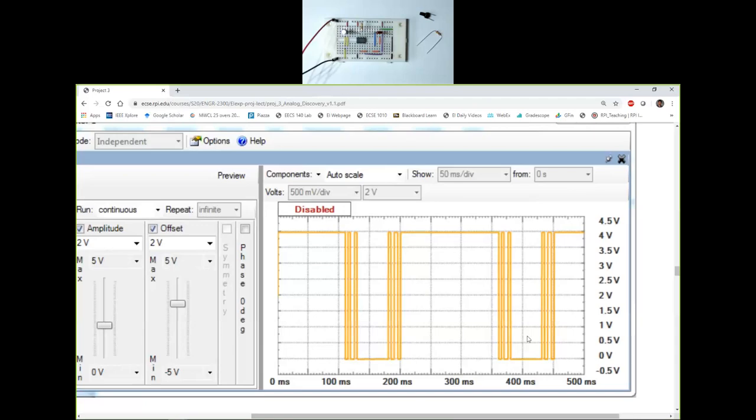a fake data that is essentially in a CSV file right now. We are going to import that, and it's going to look like this, where clearly those two instances are where the bounce happens, and that's the high state, that's the low state. So we are going to see if we can debounce this fake switch first. Our goal is to obtain an output which stays high, goes low, and then stays low for quite a bit, and then comes back up high.